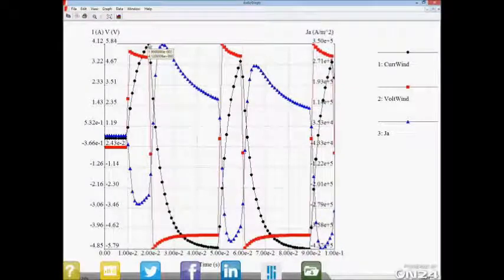When the voltage reverses, the current drops, and the time is long enough on the -5 volts that it reaches more or less a steady state. And it rises and falls again, and as is very common in pulse-type sources, you see that the very first pulse is a substantially different height than the following ones. So the initial transient behavior needs to settle down somewhat.